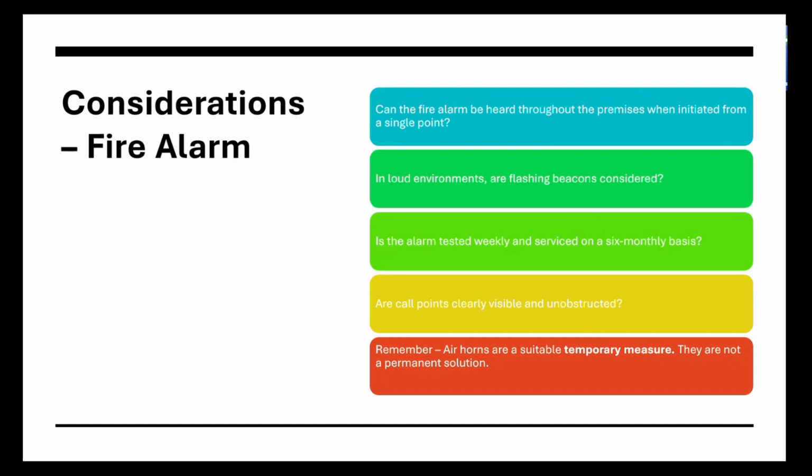So just be aware that the manual evacuators, whilst they're not a hardwired electronic fire alarm, are Bluetooth or Wi-Fi connected, and you can connect them around your premises, as many as you want, up to about 40, and they will set off the alarm around the premises. They're also fitted with flashing beacons, which is a massive help in loud environments.